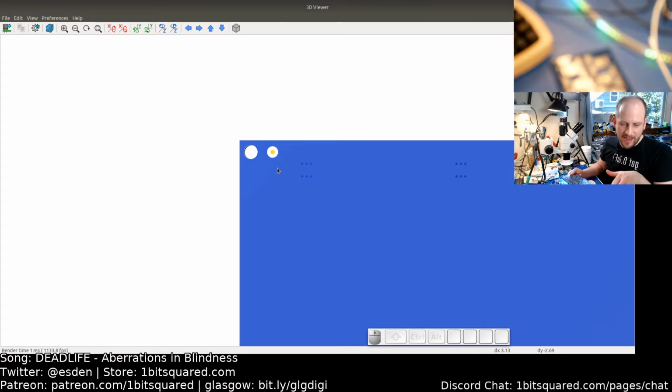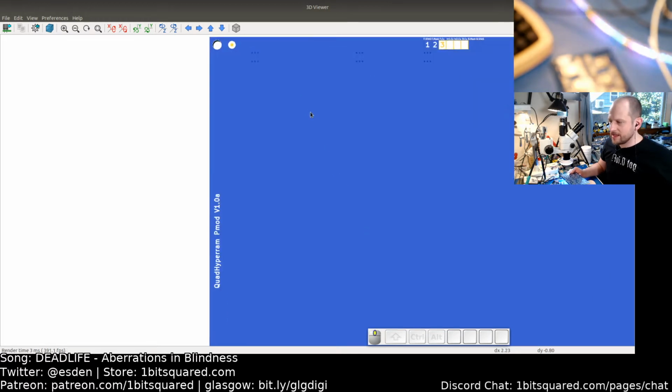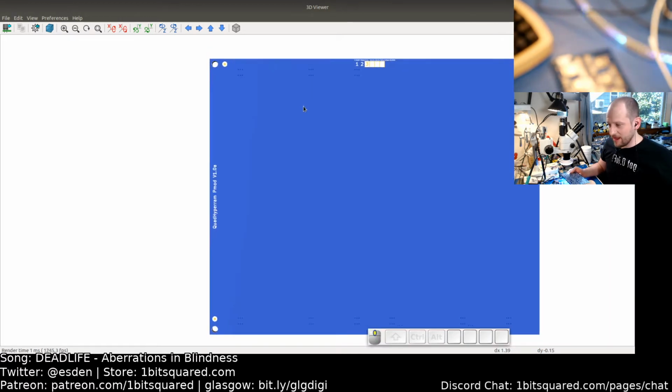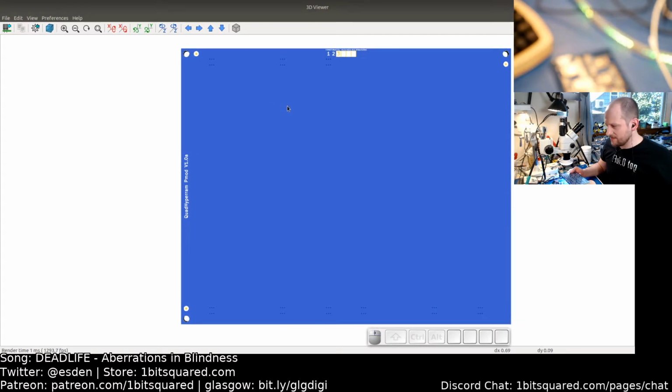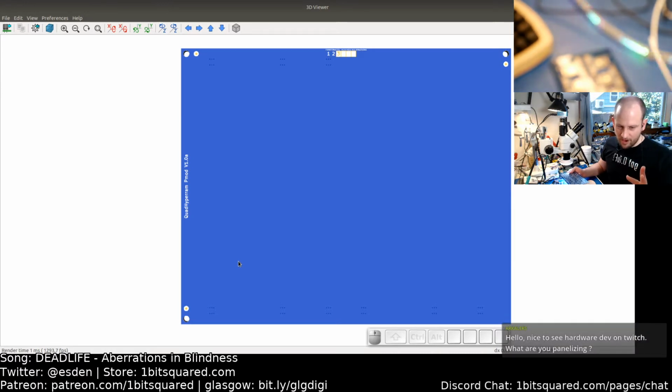No matter how mechanically accurate the PCB goes into the board, there's always some variation and some movement, so you want these visual markers. The thing that I had to learn with that, because I couldn't find good documentation for it online, is you put 3 markers on the board. The 3 markers in an L shape more or less on the board or locally for a board. And what I thought was, oh, more is better. So I kept adding more fiducials in a symmetric way.